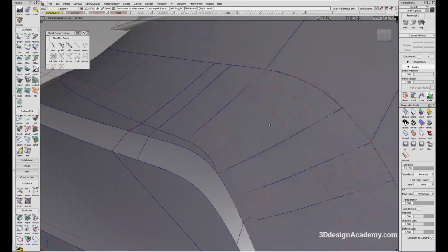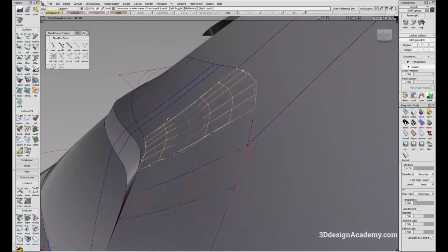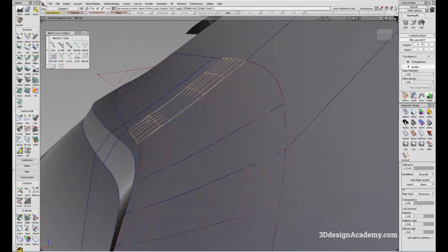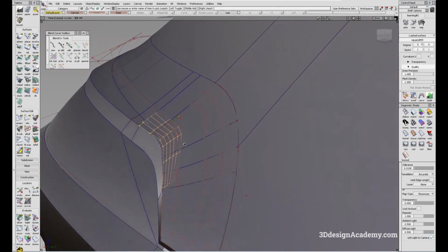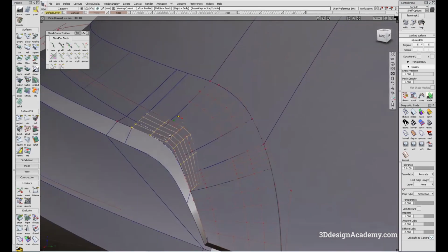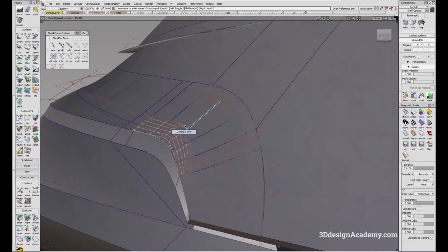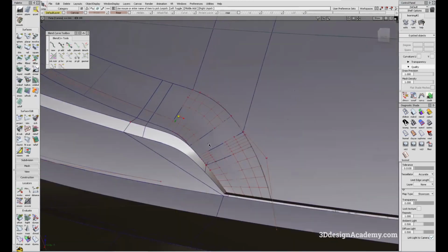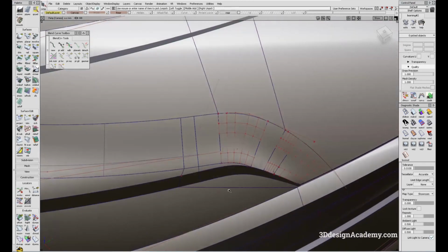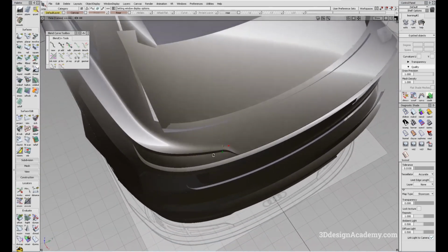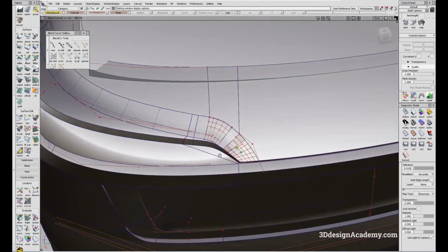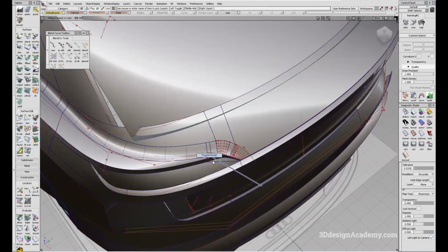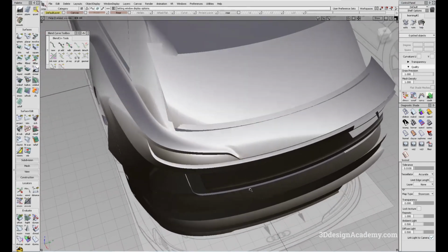I think one of the reasons why it's doing this is because you'll notice a CV structure that's actually dipping down over here. We don't want it to do that. So I think what happens is because this fillet is actually not that balanced. If you see the theoretical line here, the fillet is much closer here than here, which means I probably need to do a little adjustment over there. And you'll notice that this dip is a little bit more apparent here, and it looks like it's dipping down here. Yeah, I probably want to fix that. So if that's the case, I probably need to rebuild the whole thing.